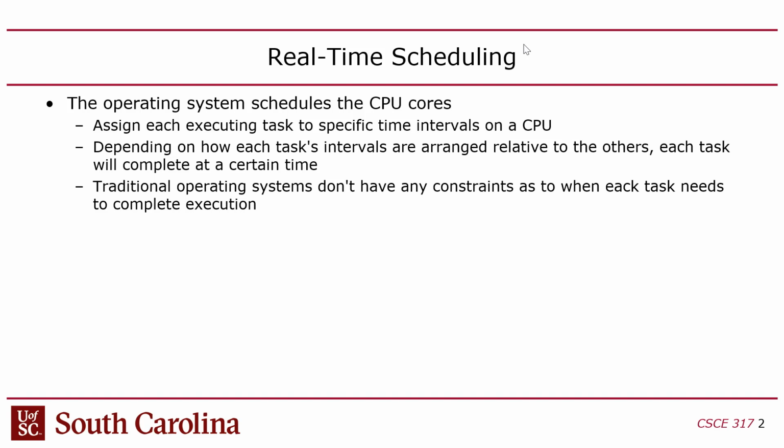But if you think of control theory, like we talked about last lecture, where you have a control algorithm that has to run every so often, imagine that as a task. It is often the case that you have multiple controllers running on one CPU, or on a set of CPUs, but the number of control tasks may be higher than the number of cores. So you have to have the operating system determine which of those tasks is getting run on a CPU. Does that make sense? Okay.